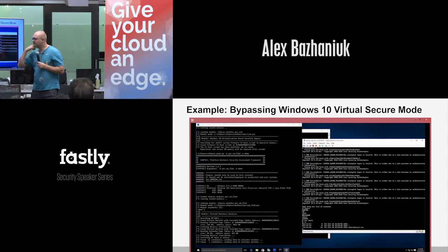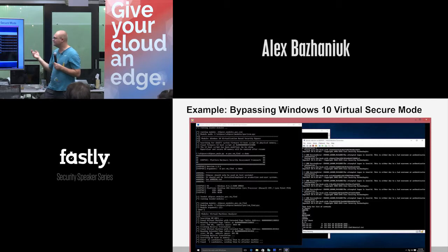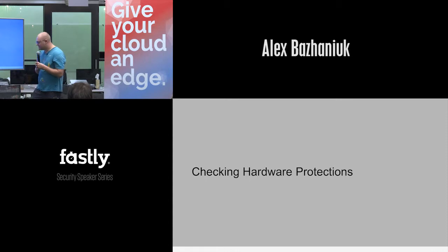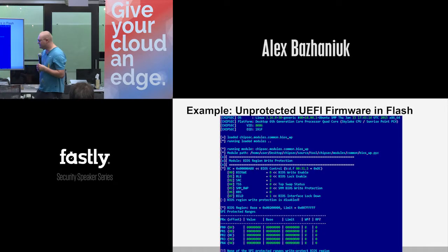So we built this attack and demonstrated it a couple times previously. This one specifically through S3 boot script, but it can also be done through SMI pointers and MMIO BARs as well. Checking hardware configuration. That's one really important check that is supposed to be properly implemented in all x86 systems to lock the BIOS, to prevent direct write access to the BIOS.